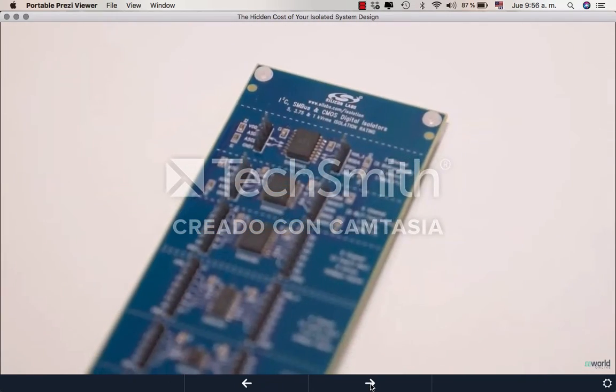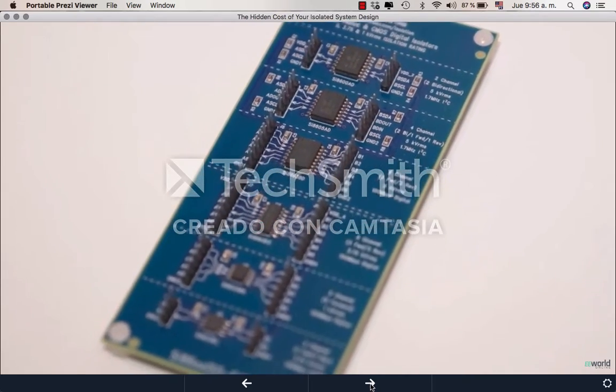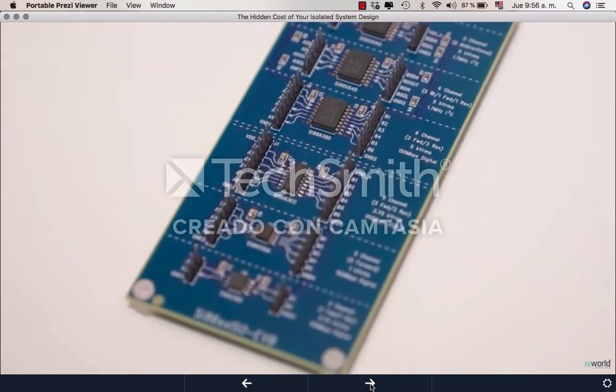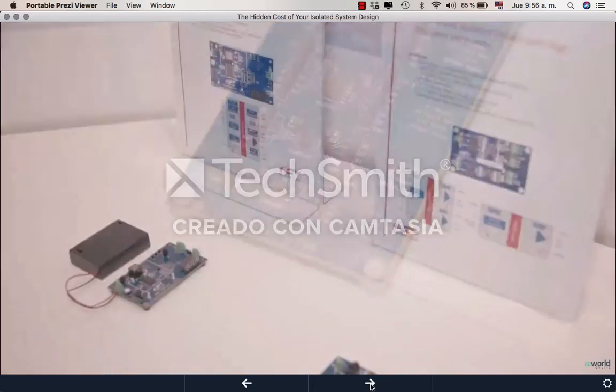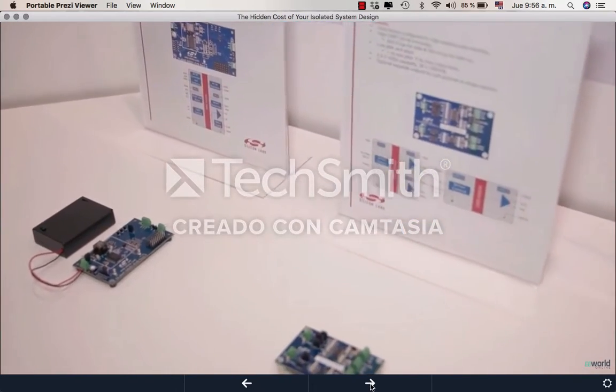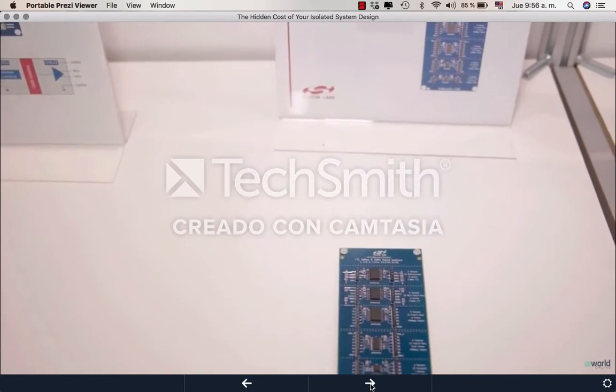So we can interface to MOSFETs, IGBTs, or even GaN and silicon carbide. So we provide this full interface to allow products operating in a low voltage domain, like an ASIC or a FPGA or MCU, to control high power domains for a variety of applications.